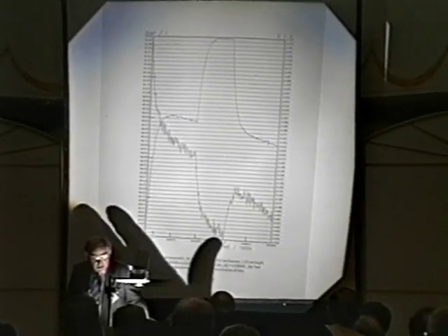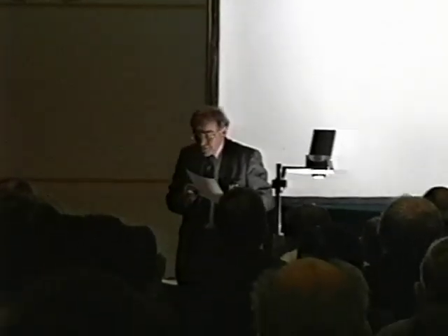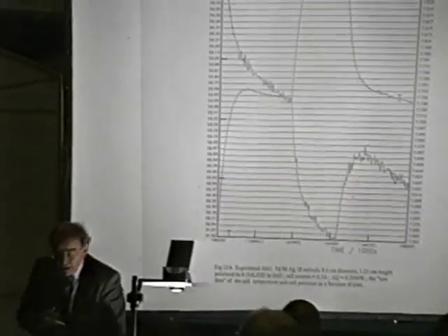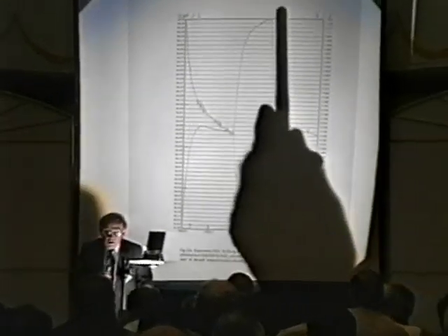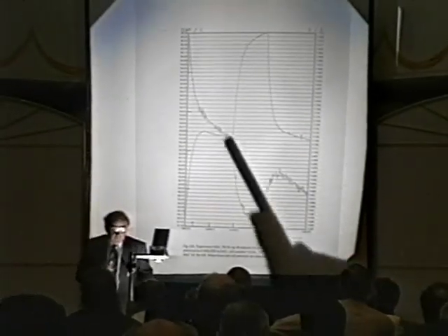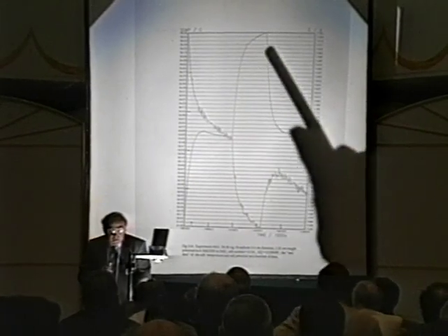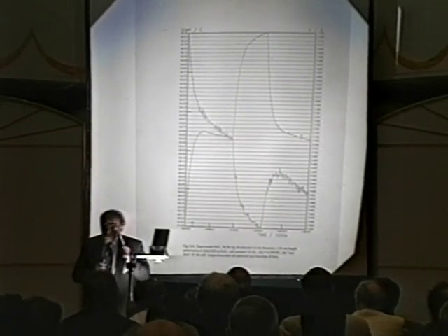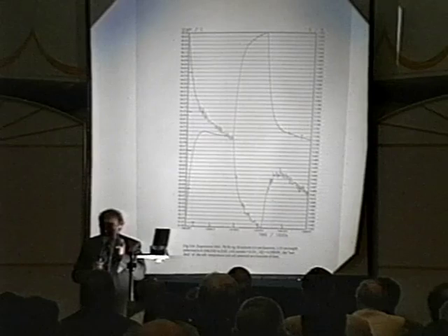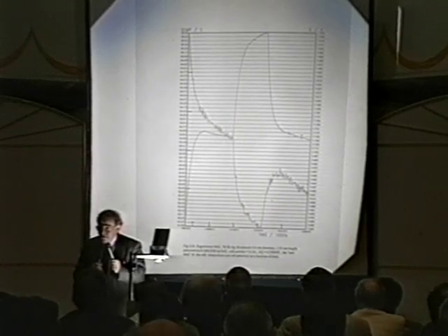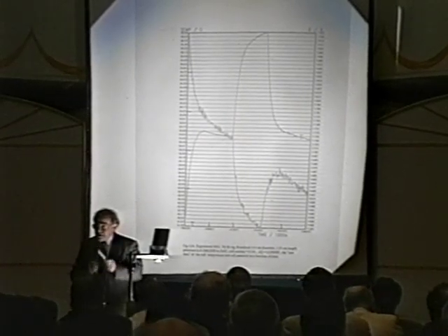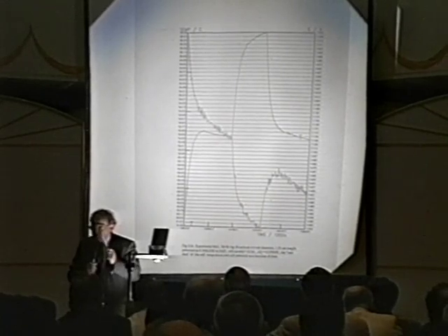But if we go at an intermediate time, if we don't go that far down the road, then we see a very curious feature of the calibration, and that is that we now don't equilibrate. We have a long tail. The temperature continues to increase. So the temperature is increasing in response to the calibration pulse. If the temperature is increasing, the heat output is increasing, and that is positive feedback.